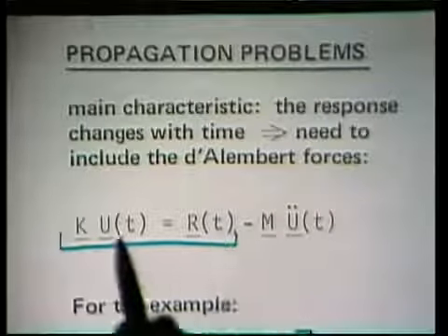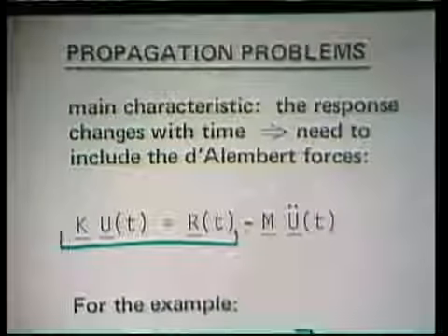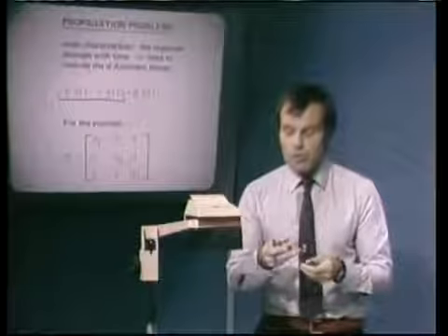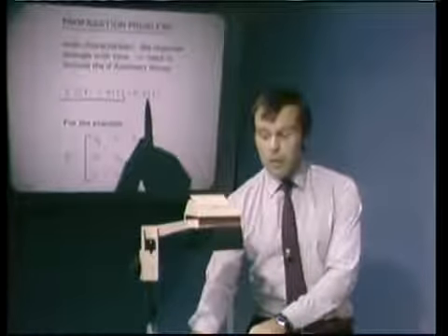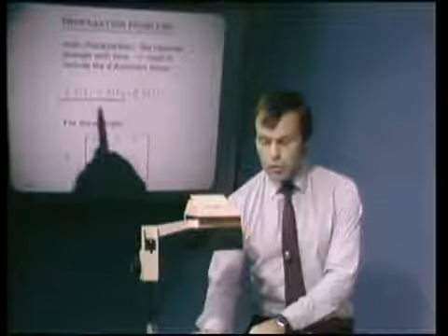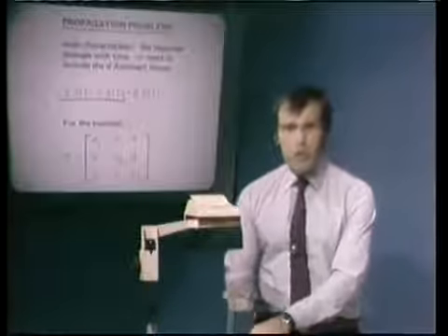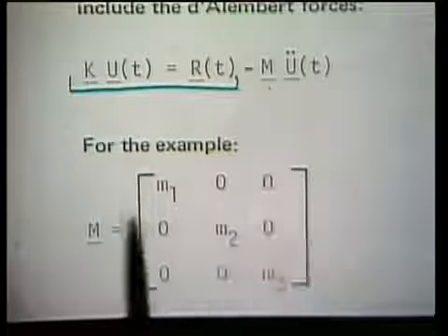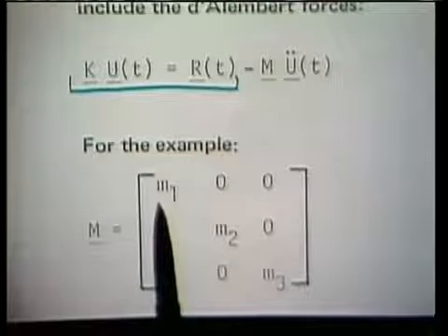Of course, if the displacements vary very slowly, in other words, the loads vary very slowly, then the inertia forces can be neglected, and we would simply have this set of equations where R of t is a function of time and U of t would be a function of time. However, when R of t acts rapidly or suddenly initial conditions are applied to the system, then the inertia forces can be very important. We have to include their effect, and then we have a true propagation problem, a truly dynamic problem that has to be solved.